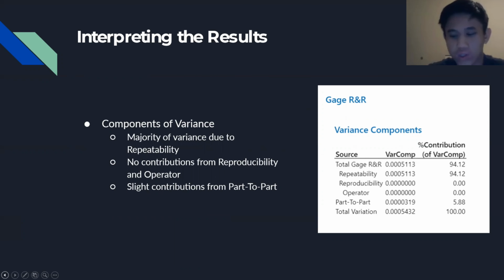So for example, there was no variation involved with using a ruler, and that there was no variation due to the flaws in the ruler. So the repeatability and the reproducibility make up the total gauge R&R, and the rest of the variation comes from the part-to-part aspect of the process.